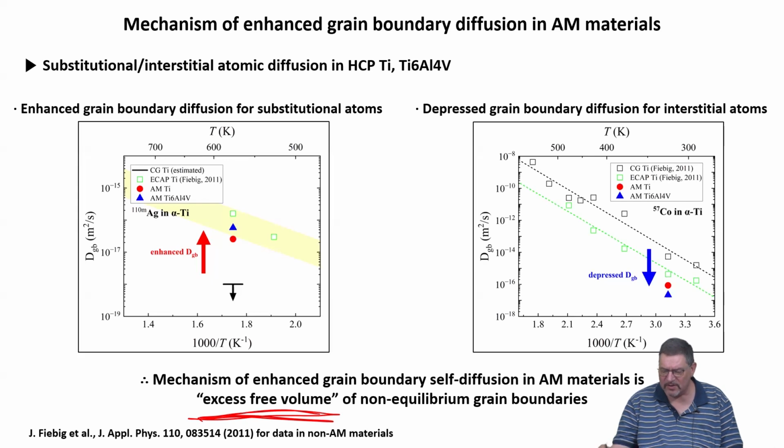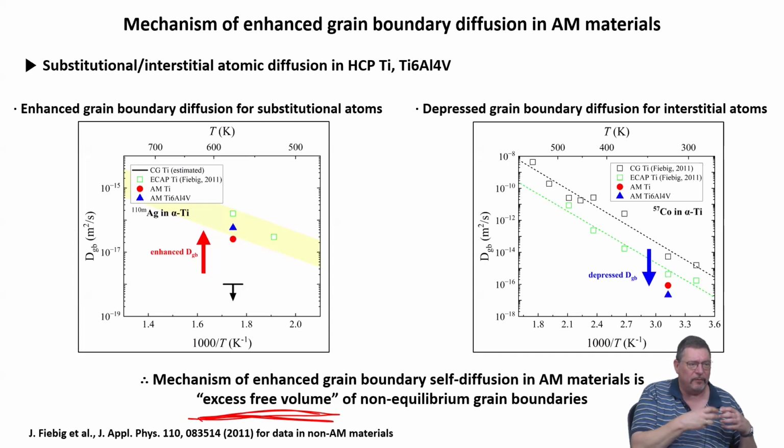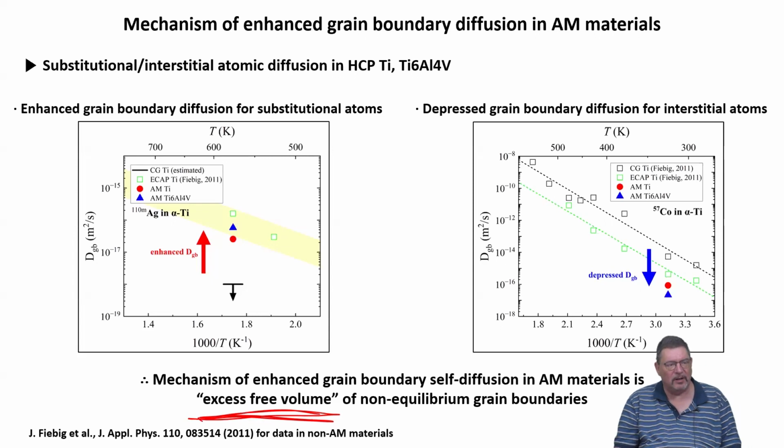So it's somehow a distribution of excess volume, probably because vacancies and dislocations find grain boundaries as a sink. And for both of them, a grain boundary doesn't have infinite depth as a sink. So there is a lot of dislocations and vacancies you can store in a grain boundary, but the grain boundary structure will be affected. And apparently it serves to make these non-equilibrium grain boundaries. And it doesn't matter if you have a thermal pathway or if you have a mechanical deformation pathway.